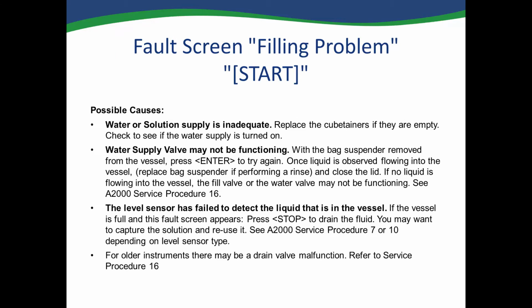The next filling problem is typically a cubitainer that has not been refilled and doesn't have enough chemicals to fill to the level sensor. Also, this can be caused if the valves have not been flushed regularly. It may require you to flush your valves or fill your cubitainer.